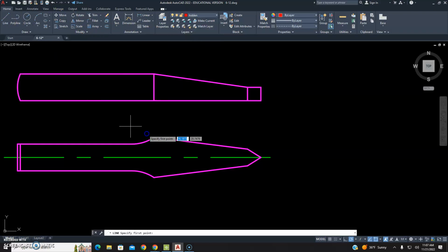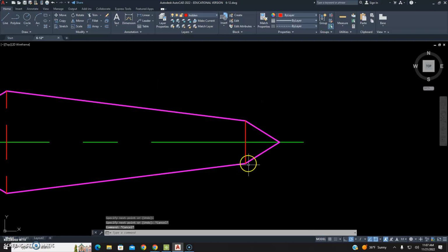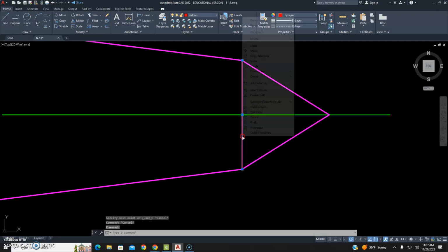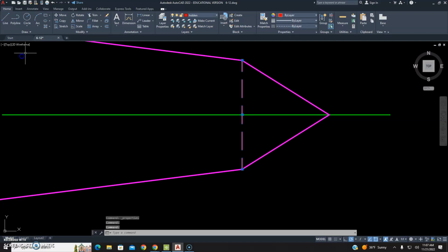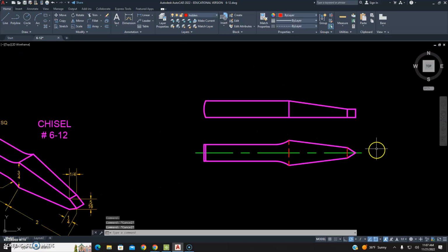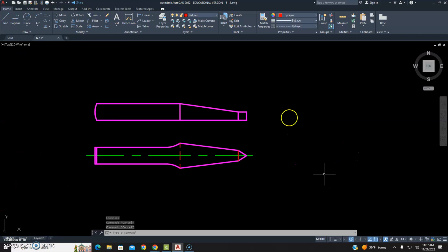So let's draw in our hidden line here. We'll do another one right here as well. Now this one doesn't have a dash, so we definitely need to lower the line type scale on it. I think 0.3 should work nicely for that. Let's try something. Let's try that 0.2. 0.2 looks good. Okay. All right, so there is our front and top view. So our side view is going to be like an end. Almost as if it's pointing at you like someone's throwing a dart at you.